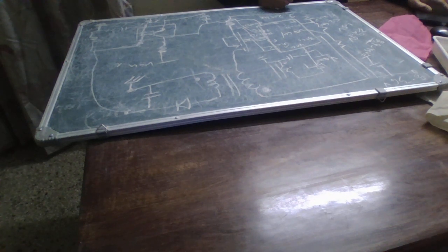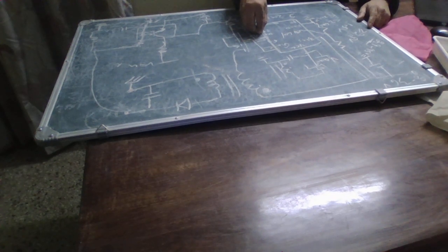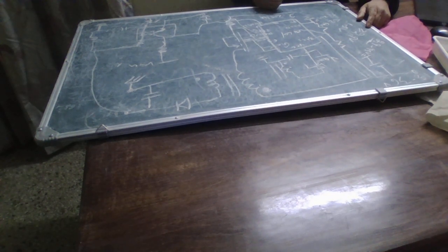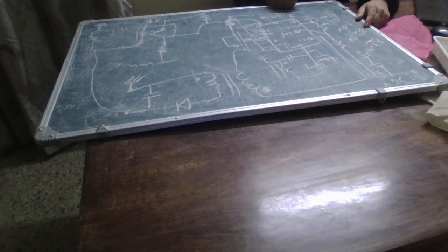Let's see what the pins are here. We have the PGND pin, the power ground pin, which is the source connection to the internal N-channel power MOSFET. We have a VCC pin, the internal VCC regulator output, which is the supply voltage input of the internal MOSFET driver. We can connect a 5 ohm resistor in series with a 1 microfarad ceramic bypass capacitor from this pin to ground.